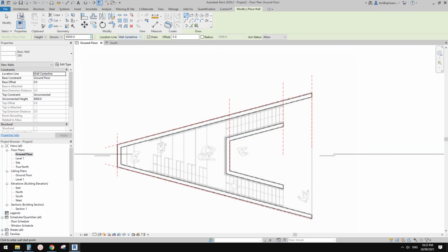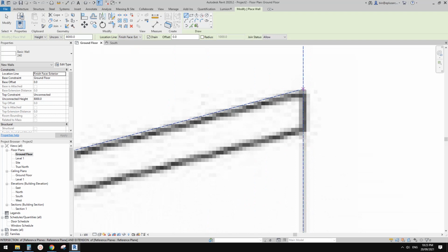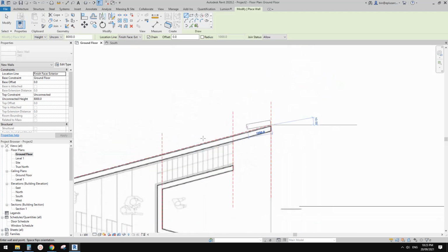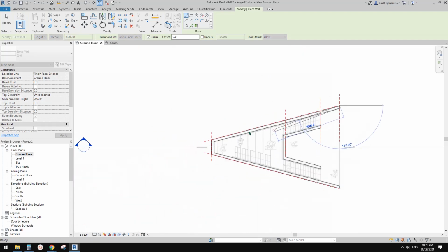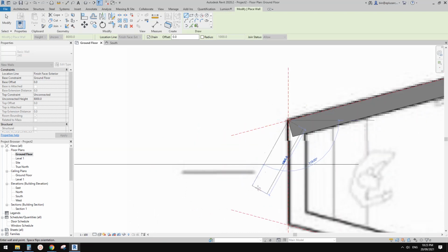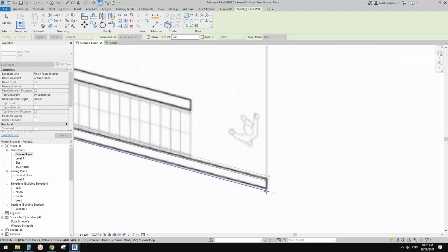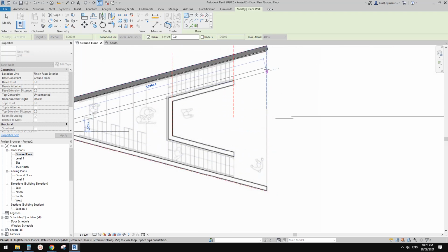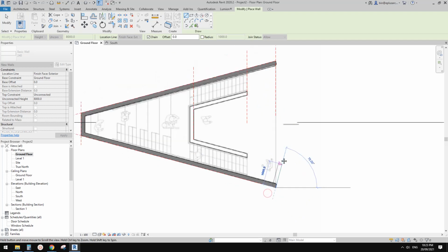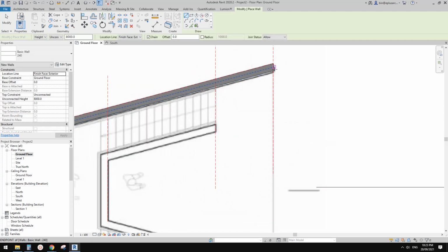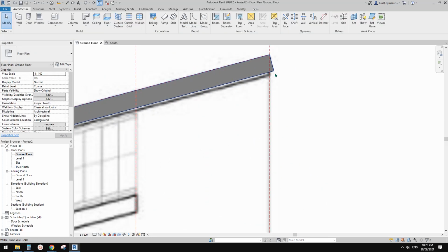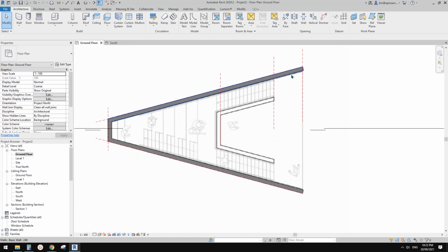So now change this to finish exterior, so we can just directly start from this point and use your spacebar and flip the wall and then finish it here and continue to here and continue to, looks like we need to extend to, so see this one go down here, so there will be this intersection point. Okay, so finish it. So you will see this little bit, so we can use void to cut that, so we'll just leave it for now.